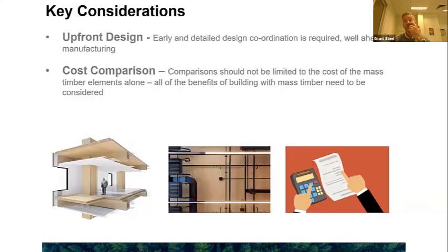A couple more considerations. Upfront design. So mass timber requires a significant investment of upfront design, more so than traditional in-situ concrete. Good example of this is early coordinated building services. It's recommended that penetrations and the like be considered in combination with the structural and fire design. Otherwise, you may be inviting a little bit of trouble in terms of manufacturing delays and possible redesign costs.